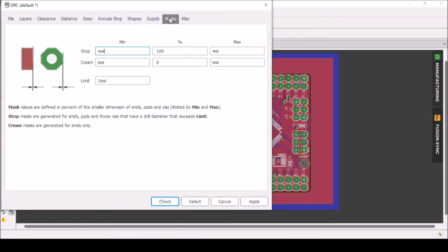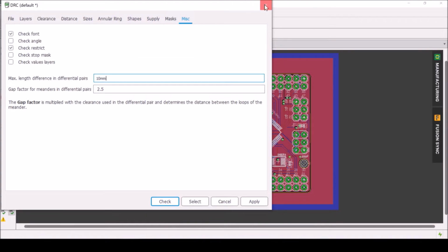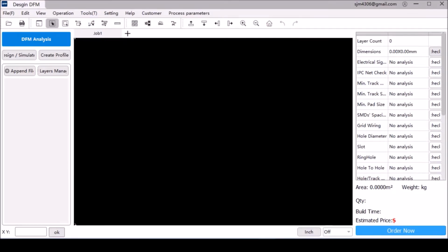DFM within my PCB CAD editor. In this case, I use Eagle. 2. I run a second check using NextDFM with the exact same criteria. 3. And finally, a big step is to use both the simulation and design image modes within NextDFM to visually inspect for obvious flaws that might affect soldering or use of the final board that isn't necessarily caught with automated